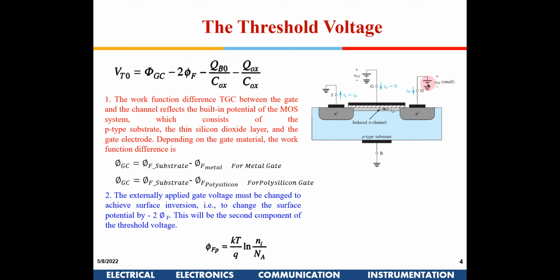Now if you scale down the VDD, you can't keep VTH the same, right? You will have to reduce VTH, because we saw in our first class, and will see in today's class also, in the current equation, greater VT means lesser current. So to keep the currents constant, I need to reduce VT. One way of doing that is known as gate engineering, where we use a different, appropriate metal, so that we have a lesser VT.